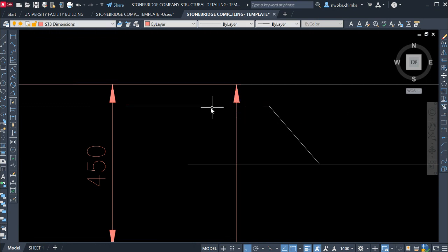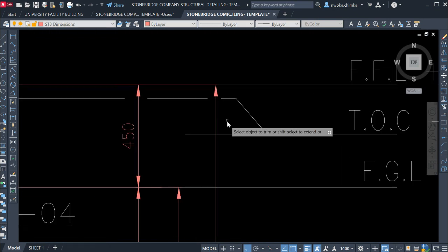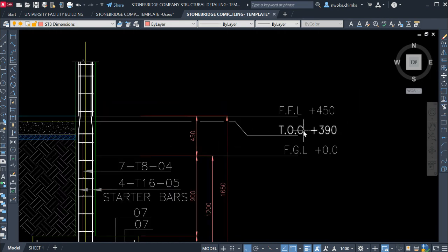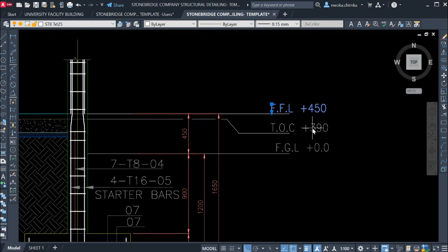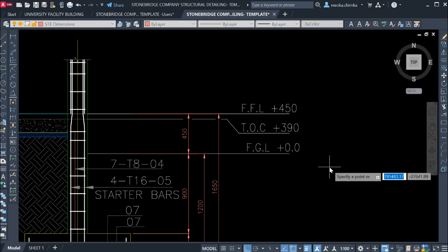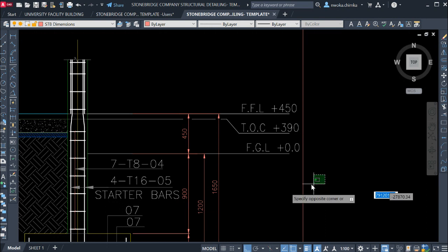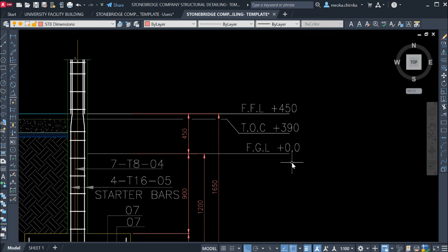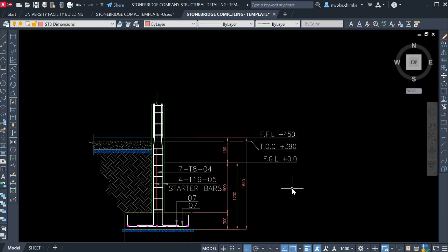Click here and also click here, and then click on TR, trim, off here, and then try to bring this backward a bit because they are already too long. Bring them backward a bit and then try to extend a line, to place a line here first. Now XL, enter, V, enter, place a line here, click on this, XL, and then do this and do this and do this also, and then remove this and keep it here. Okay, so now you can see what we have just gotten.